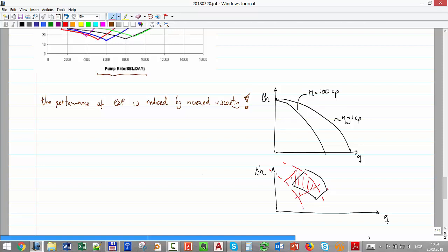And that's especially important, going back to our emulsion, why this guy is talking about emulsion. The water cut in a heavy oil field or in a water flood project is going to initially be 0, and it is going to increase to maybe 90%. Then you're going to pass through the whole range of this emulsion.